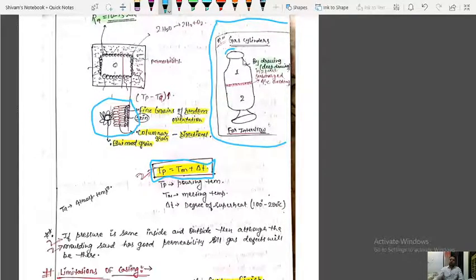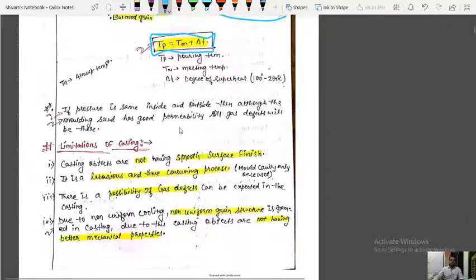Drawing is used to make these metallic sheets, and in between you will see that there is a weld done all around the middle portion of the gas cylinder. In the interview they will ask which type of welding process is used to weld this gas cylinder, and submerged arc welding is used. You have to remember this. Then we will move further.